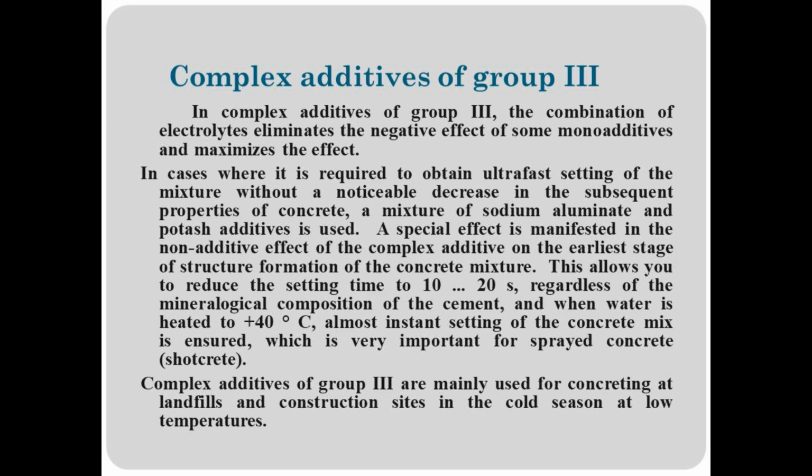This allows you to reduce the setting time to 10-20 s regardless of the mineralogical composition of the cement, and when water is heated to 40 °C, almost instant setting of the concrete mix is ensured, which is very important for sprayed concrete, shotcrete.